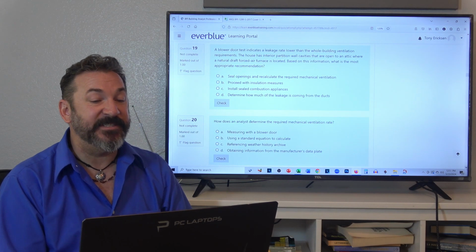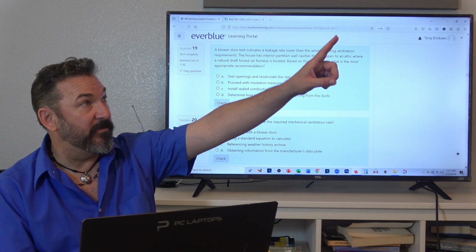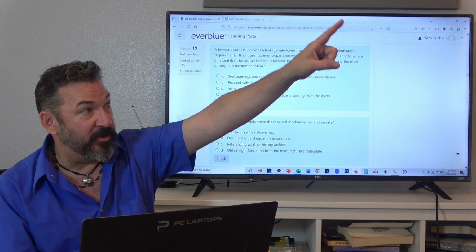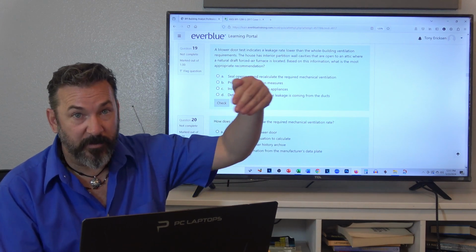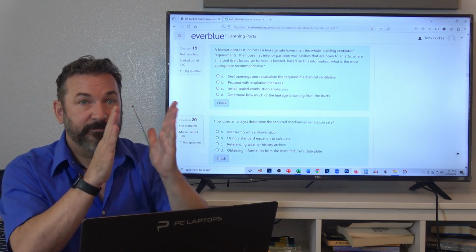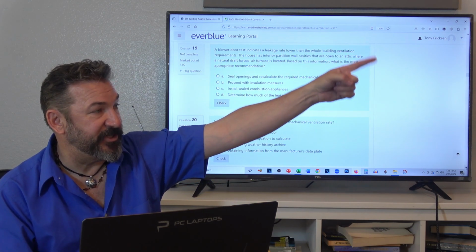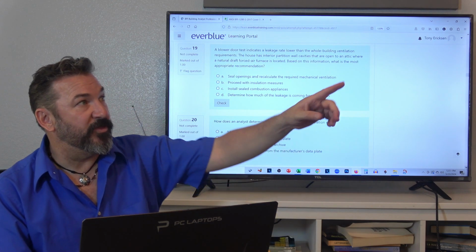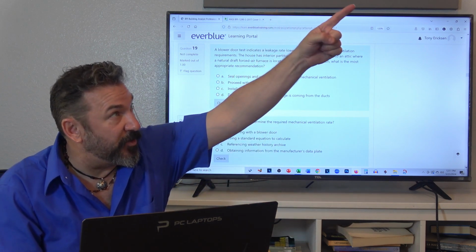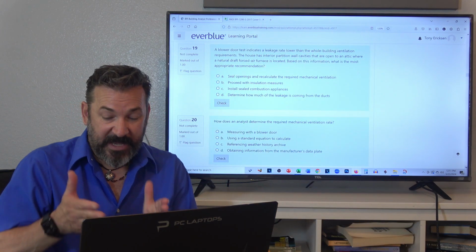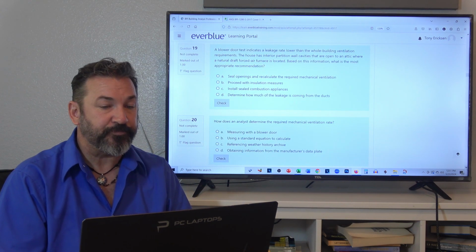Okay, the house has interior partition walls that are open to the attic. So like where this little knee wall is right here, the partition wall could be open. I haven't gone up there and poked. What's a partition wall? An interior wall. Yeah, the knee wall just separates that room from this wall. So this wall right here, that's a partition separating the kitchen from the living room. Oh, okay. So there might not be a top plate. Those studs could go all the way to the top, to the floor. There's no top plate. It could just be like a balloon frame and completely open all the way. So that's kind of what they're talking about here, okay?